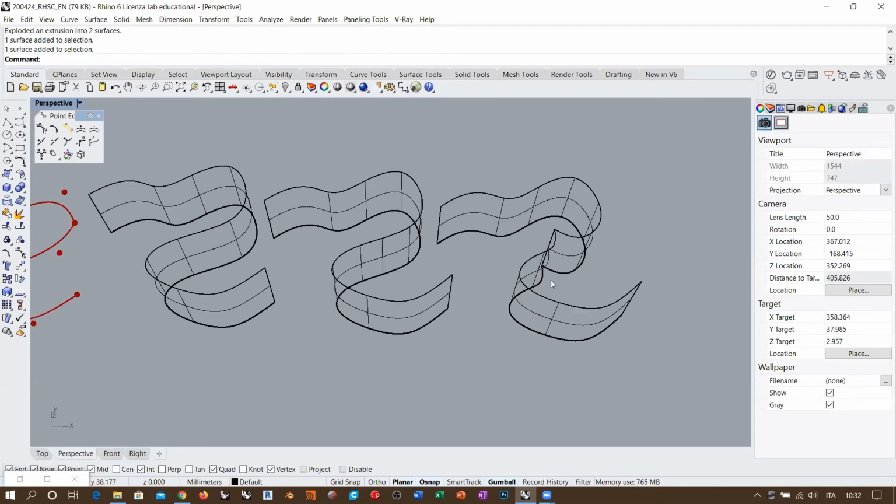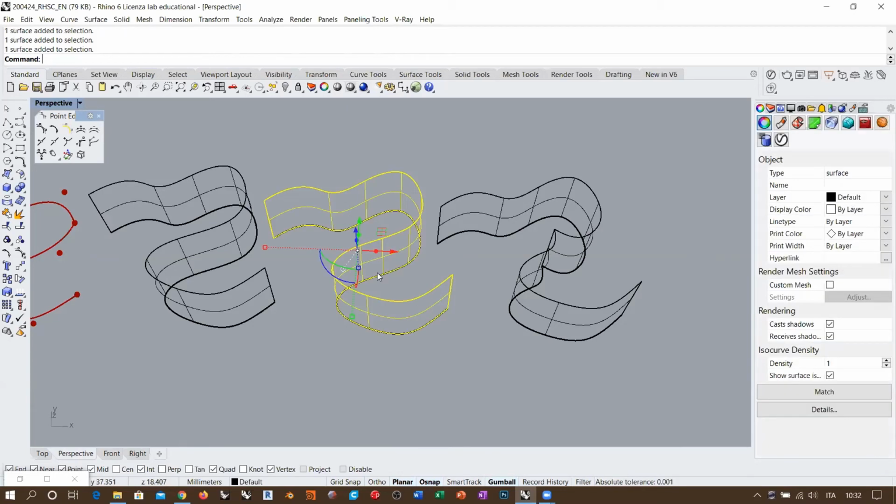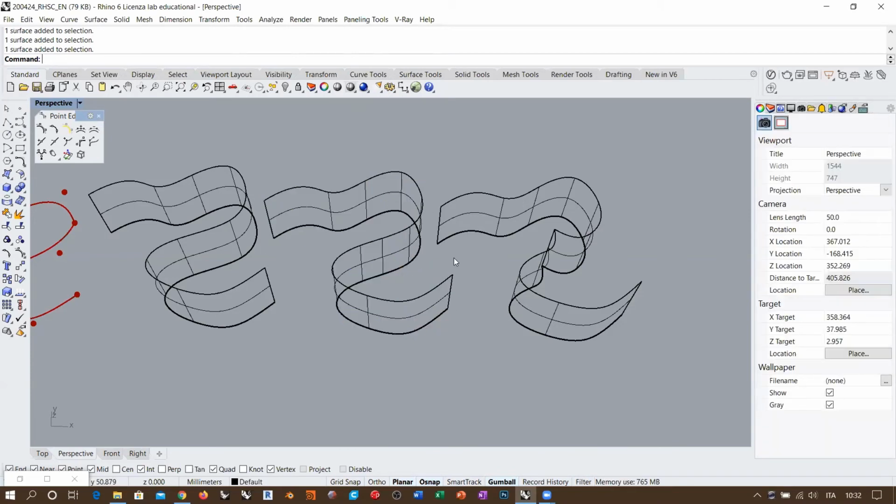So it's different to have a visible internal discontinuity, like in this case, and an invisible internal discontinuity, like in this case here. Because if Rhino detects that discontinuity, it converts it into a physical separation along the extrusion. While if you keep it hidden, like in this case, you perform the extrusion, the kink converts into a kink line, and you get one single stripe, one single surface that you can work with in a simpler topological workflow.